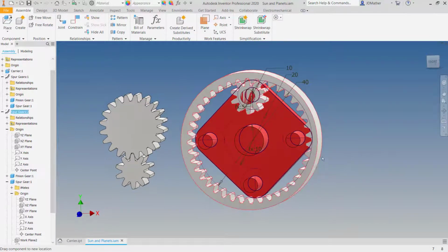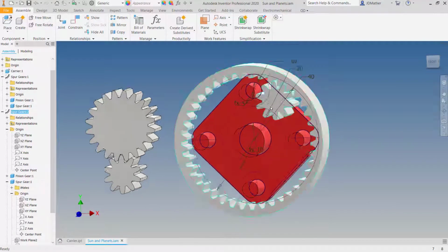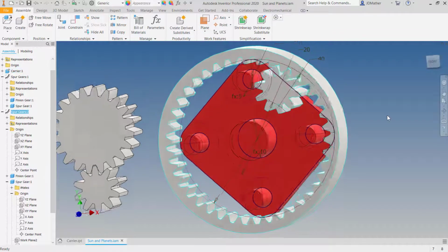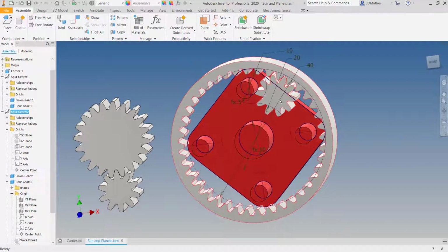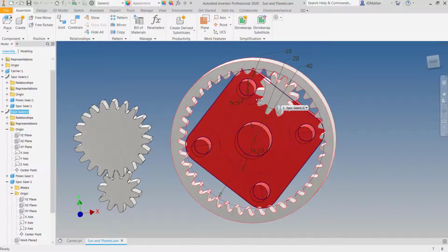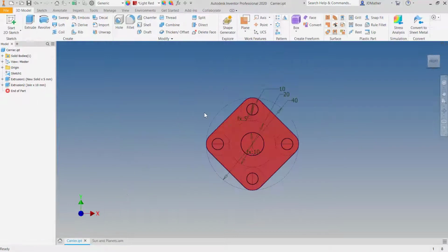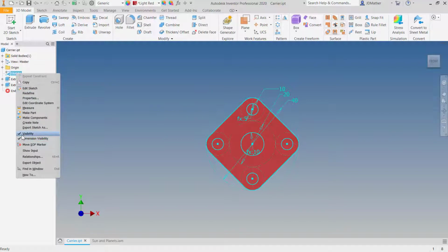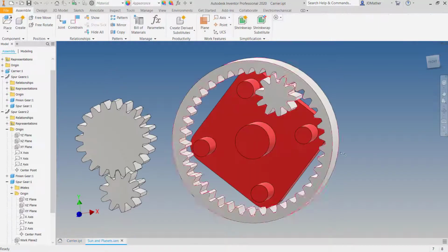And then if we drag this, we see that this rotates. And so I'm going to put an insert between here and here. And I think what I'll do is put a hole into that gear to put onto this pin. And let's do a couple of things first. Let's turn off the visibility of these dimensions. We don't need to see that sketch anymore. So I'll hide that. And I'll go back to my assembly, and I'm going to do shift right click. I'll go to part priority.